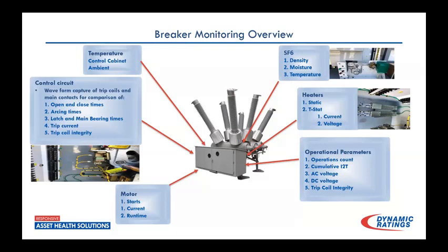I had a lot of OCB breakers when I was at the utility, and would find that the cartridge fuses had gotten so wet that they had just disintegrated in the holders. And again, now we have a fail to operate that comes into play. Wire that had become so corroded that it just broke out of a terminal block. So these are why these things are important. And then when we get into talking about online monitoring, it's much like offline testing. It's important that we have something that's capturing that timing.